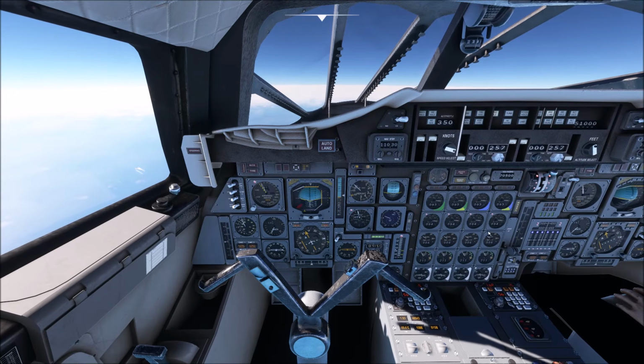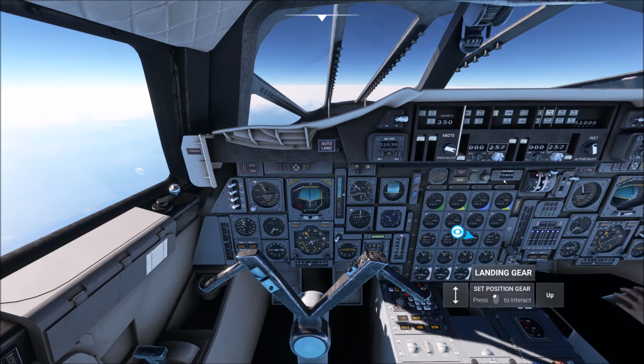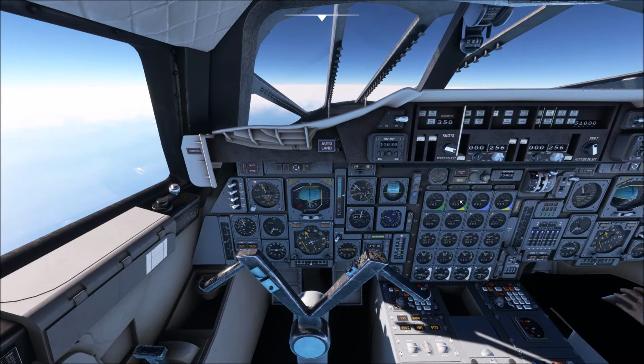24 tonnes per hour fuel burn. Basically something under 3 hours of fuel. That will reduce as time goes on because we're still in a climb a little bit. That gets down to sometimes about 12 tonnes per hour. So you can see, as we get higher of course it will get better and more efficient.